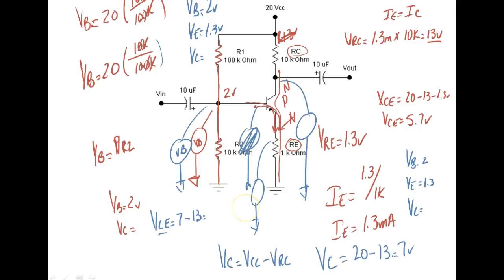And that would give me my voltage collector to emitter, which we usually don't measure. Y'all understand why? Y'all seen the transistor? Well, not yet. I passed one around. Now see how close those little leads are together? And a meter lead will not fit down between two of those things.